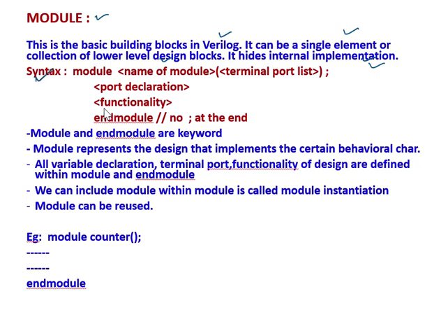This is the module syntax: module keyword, then name of the module, then the terminal port list, then semicolon. The semicolon is a must. Then we do the port declaration, then the functionality of the design, then endmodule, and at the end of endmodule there is no semicolon.